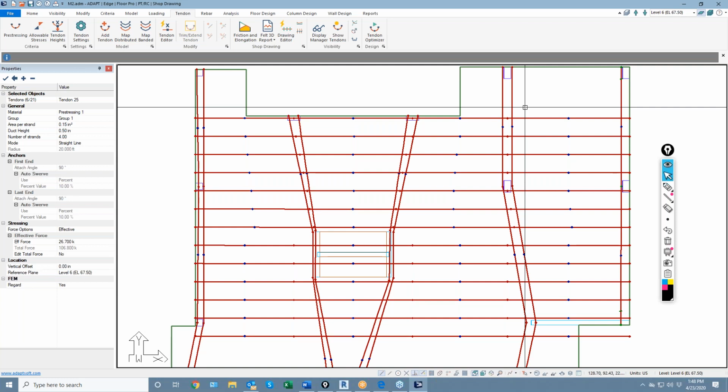That's the easiest thing to target when we're modeling post-tensioning into this type of environment. So I don't quite yet know if I need more density of cables or more cables per foot, because it's really a matter of whether we're meeting enough load balancing, whether we have enough pre-compression, and also we have to meet the requirement for the allowable stress.